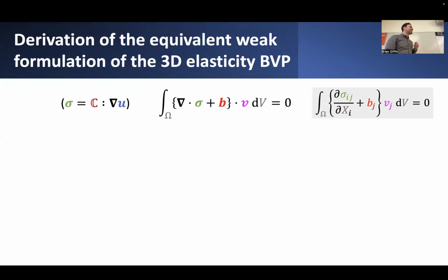So as we must, we should make those manipulations to really see how we get rid of, in particular, this term that involves the divergence of the stress tensor, the thing that was impeding our ability to remove some of those differentiability requirements on the stress tensor.